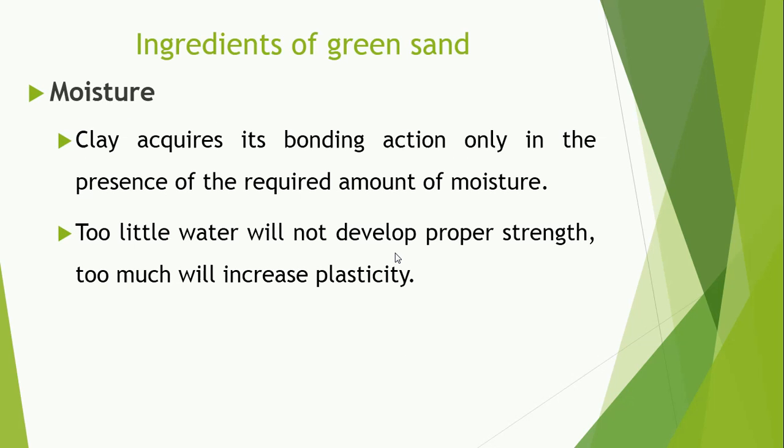Clay acquires its bonding action only in the presence of the required amount of moisture. Too little water will not develop proper strength, and too much water will increase its plasticity. That is the requirement of moisture.